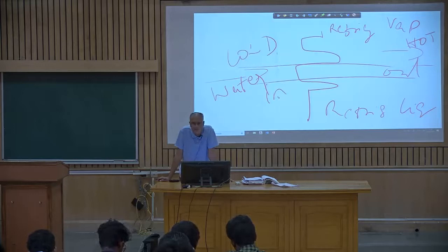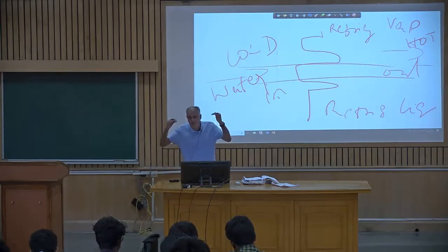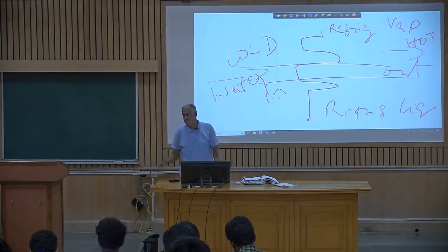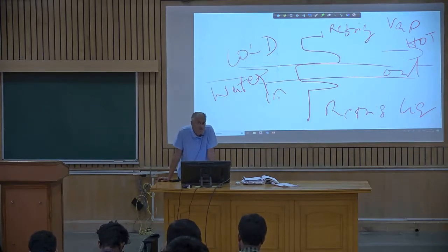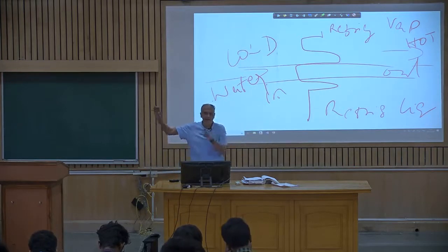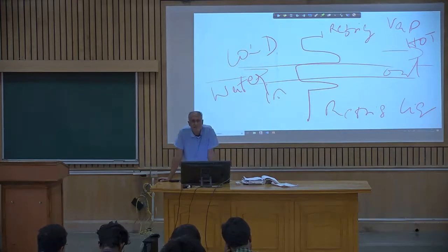Doable. So this can get slowly complicated, right? You can change the potential energies, you can change the positions. Correct? So don't think every time you have to consider it to be negligible. I can change the velocities, yes? The inlet velocities and the outlet velocities. You have to consider the kinetic energy. That's it, there's nothing. You have written the balance, right? Input, output. Depending on your assumptions, you make zeros, and wherever there's no zeros, you ask for the values.